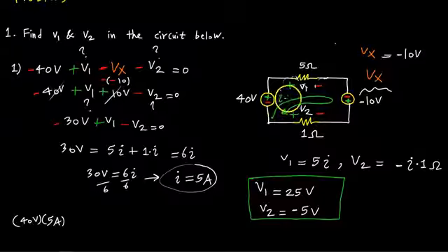But then we have to remember that current's going from minus to plus. So the passive sign convention will tell us that it has to be a minus. And which means that the power here is being sourced by that element, which makes sense. It's a voltage source, so it's going to source some power to the rest of the circuit.